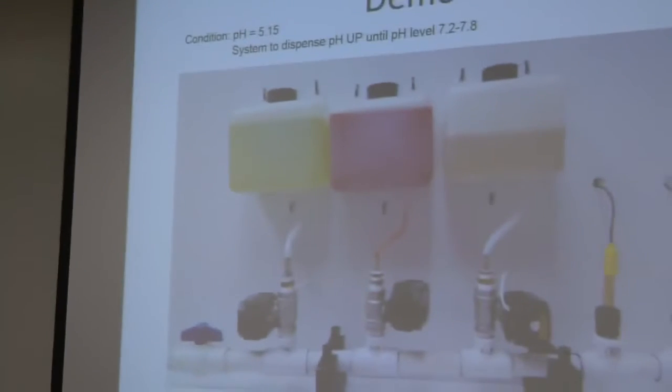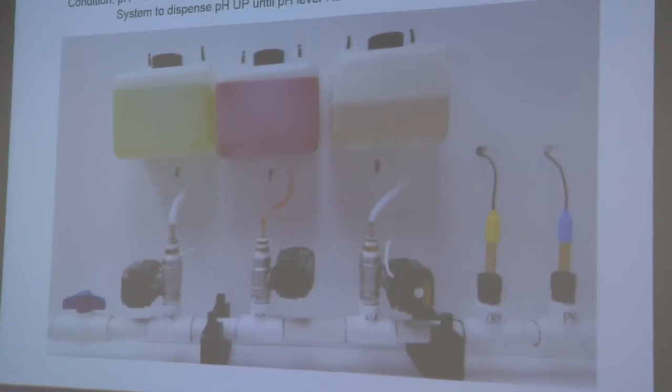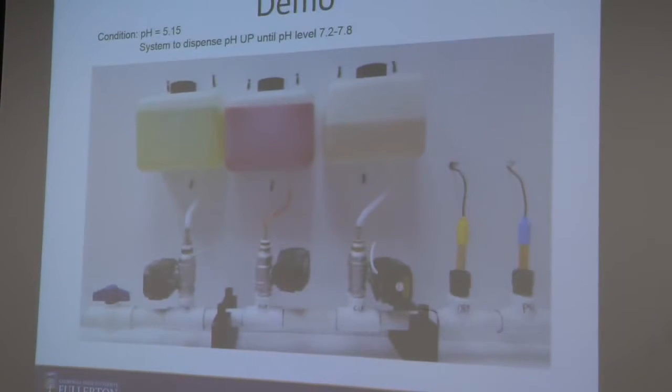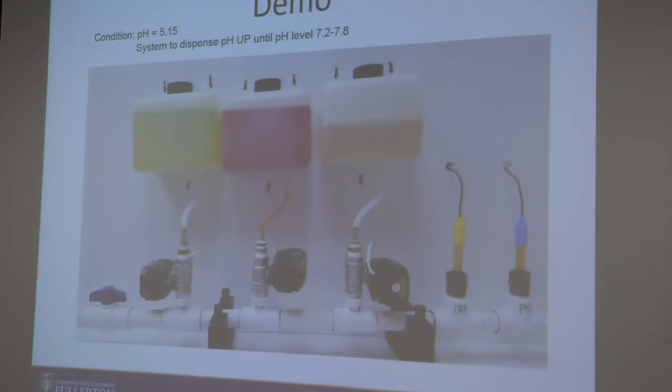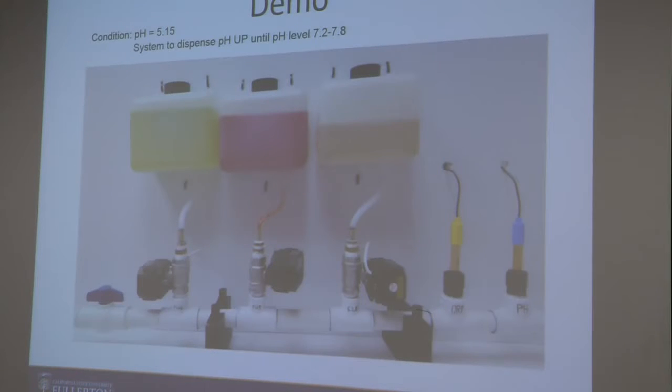So here it's dispensing pH up chemicals into the pool. It keeps dispensing until it reaches the main pH level that it wants. There's continuous water coming in through the main pipe. What it's doing is checking every 5 seconds if the pH has gone up into the area that we consider good. Once it checks, it'll keep dispensing, and I think it dispenses for around 10 seconds.